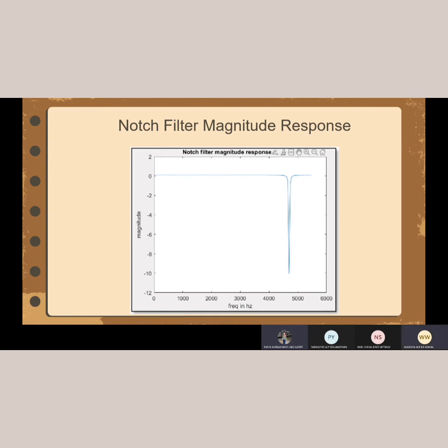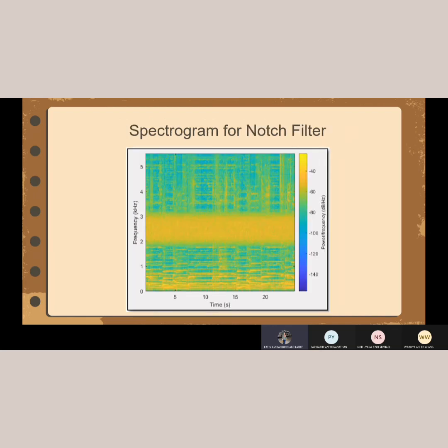From the spectrogram, there are some changes from the previous spectrogram with the notch spectrogram. The noise was removed, and the pole zero plot showed that the system is stable, and the sound is played to observe the difference. After we carry out all three filters, we can hear the clear audio.